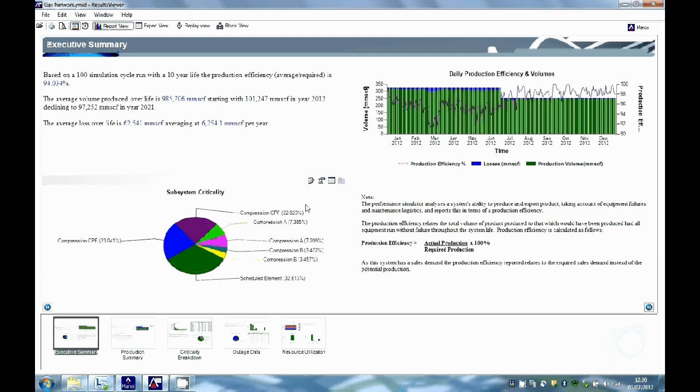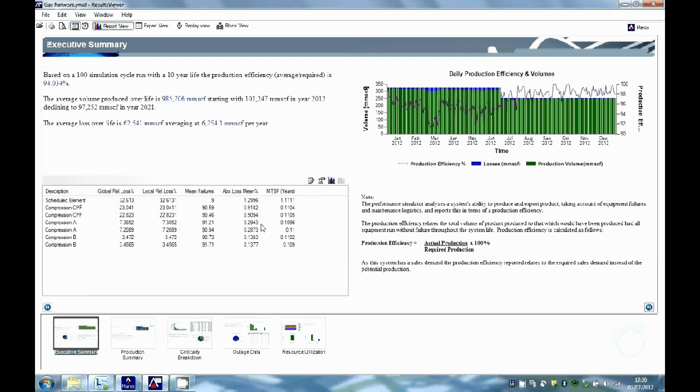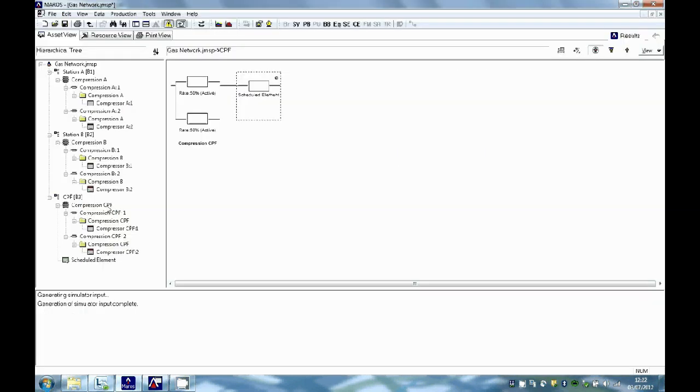If you click on the event graph, you can drill down events further into the results. And if you pass the mouse over the graph, a row at the top of the graph area will appear. Click on the third icon, which looks like a table, and the results will now appear in a table format. Right click on any of the equipment or events and select View in Maros. This button will take you directly to the equipment that is the problem.